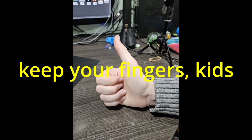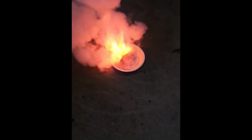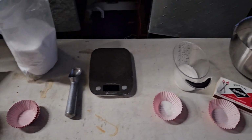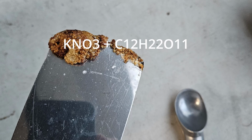Consider yourself warned. Now, let's play with some fire. One of my core engineering principles is simple is better. In keeping with this, I'm going to be using a mixture of potassium nitrate and sugar as my propellant. This is a classic propellant formula that has been a staple of hobby experimental rocketry for decades due to its reliability and simple synthesis. Potassium nitrate, or KNO3, will be the oxidizer, and sugar, or C12H22O11, will be the fuel.